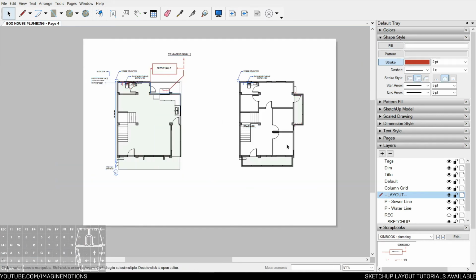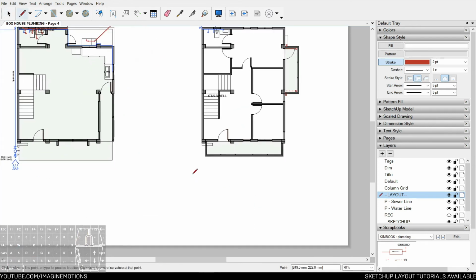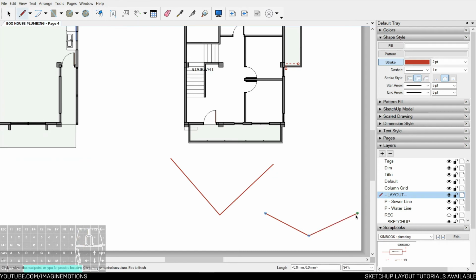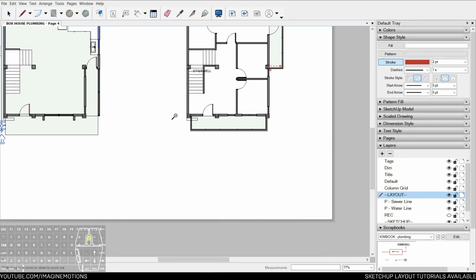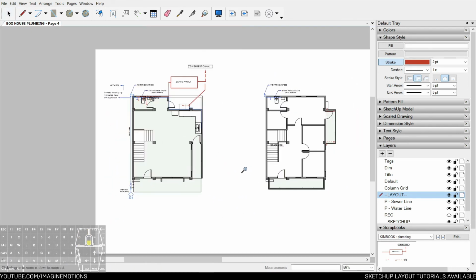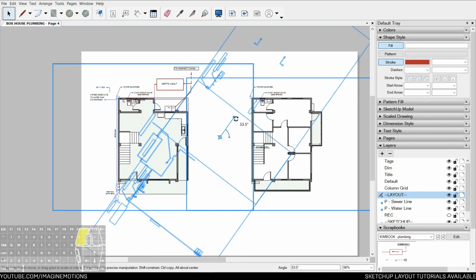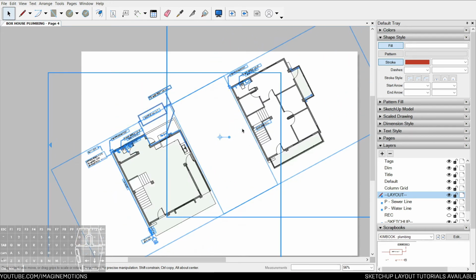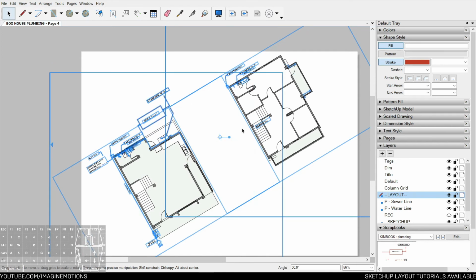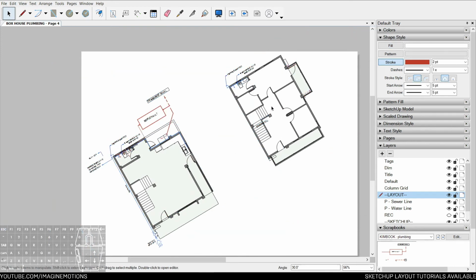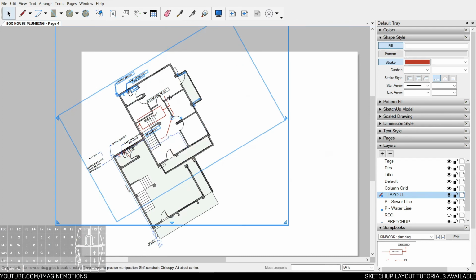For the isometric view, by standard, there should be an angle of 60 and 60 on both sides, or 30-60, or 30-30, whichever plays along 30 and 60. However, for our case, we will see which suits best for the A3 size paper. So I'm going to raise this up by 30 degrees, so type in 30, enter. And let's see if both floor plans can fit.